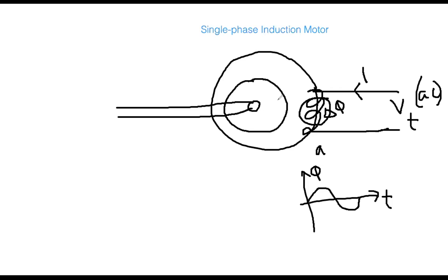The rotor is squirrel cage type, it has conducting bars. Therefore, if there were a revolving field, then there must be voltage built up on the rotor circuit. But in this case, flux is just being developed, but it is confined here. It is just pulsating, just oscillating only here. It is not rotating. Consequently, there is no voltage buildup. Then there is no current and no flux on the rotor circuit. So for example, let me say that this phi is zero. Rotor flux is zero. This is only the stator flux.